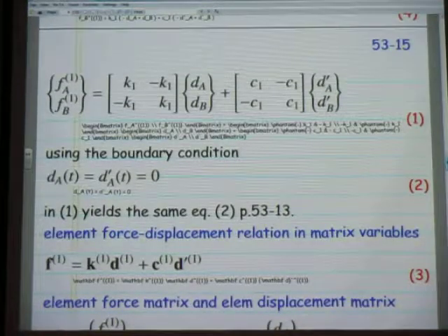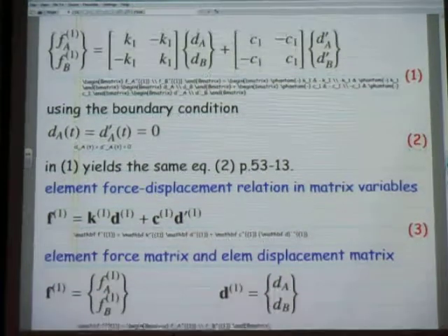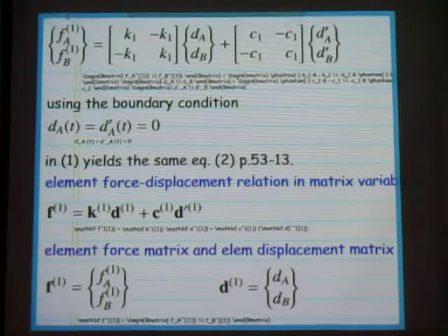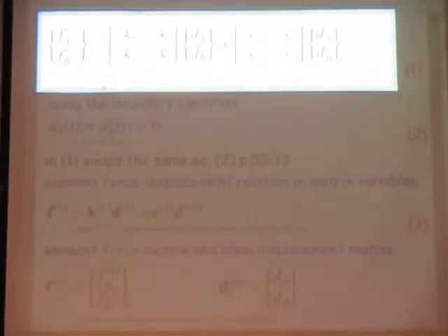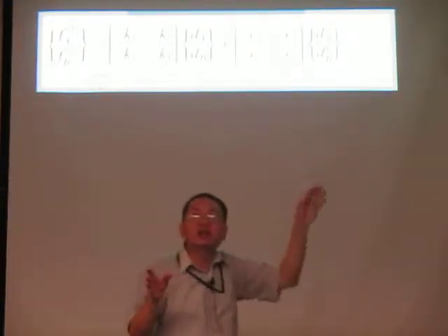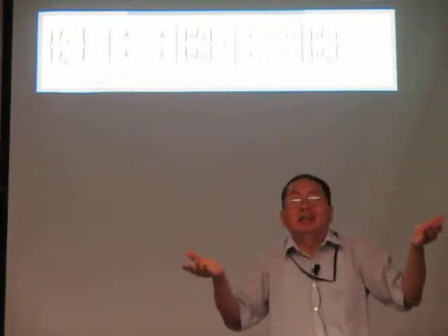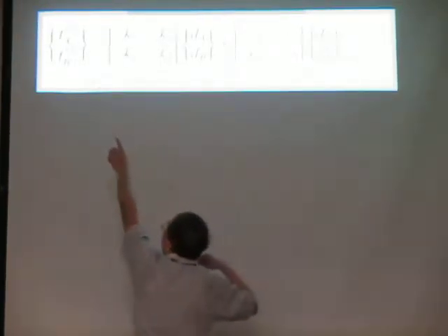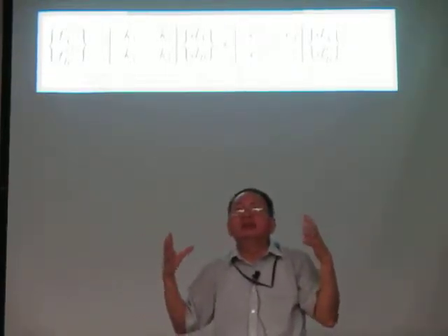All right. So let me avoid overloading information, so let's use the mask. Okay. Once you have the matrix, this is called, by the way, the force displacement relation. This is called the force displacement relation. It's basically the equivalent of F equal to KD, but more complex, more advanced. You need F equal to KD, but now you're talking about matrices.